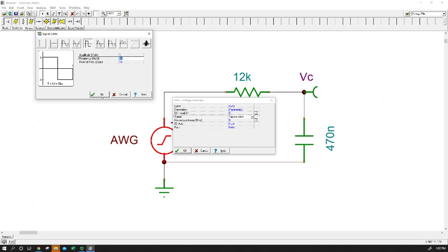So basically, if I already know what my values of resistance and capacitance are, and I know the relationship of tau to the duration of a full waveform, I can zoom in on what I think the frequency would be if I want to display a full waveform of that circuit, because it's in fact the time constant that sets the period of the circuit.